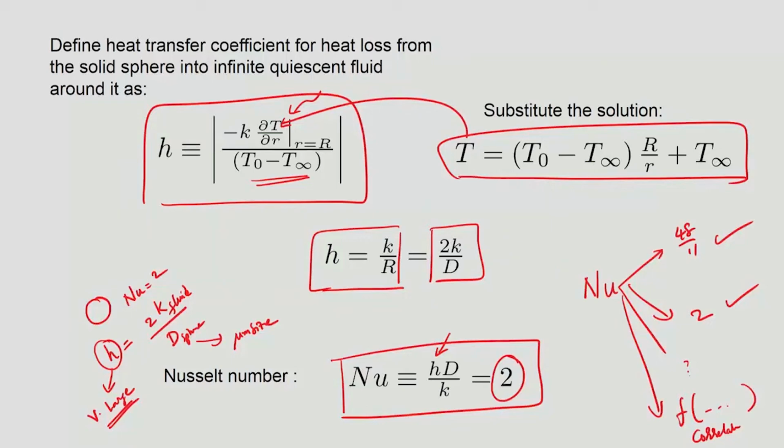So, in spray forming for metal powder manufacturing, what you are actually using is the Nu equal to 2 idea to get the h to be as large as you can, and thereby avoiding slow solidification and segregation, etc.